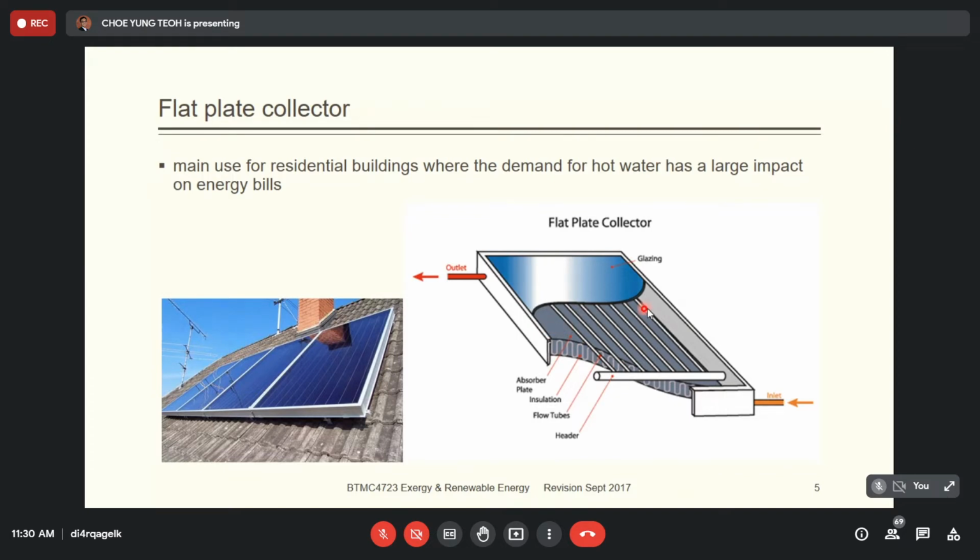So it means that I cover all the surface, which means I can absorb all the heat on all the surface in this flat plate collector. And as I said, the heat transfer rate totally depends on the total contact area. So how do you make the heat transfer into the water fastest? You have to make the surface of the copper pipe thinner with a bigger contact area. Maybe I draw a bit.